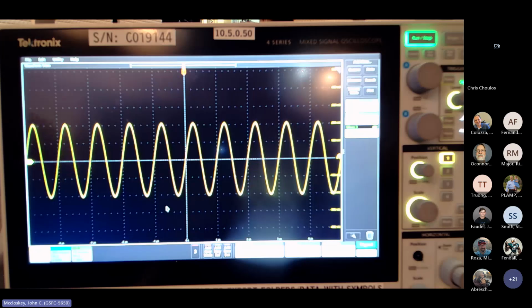So not quite our 150. So we're not quite to the flat part of the curve yet, but we're very close, because 150 millivolts was our target to correspond to a 3 milliamp calibration current. Okay. So yeah, 145 now, and I was reading about 143.5 the other day. Now I'll go to 3 megahertz.